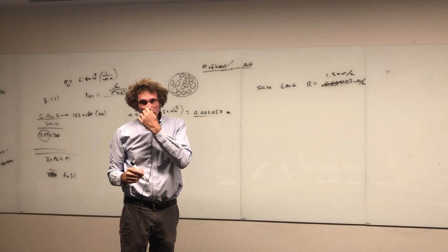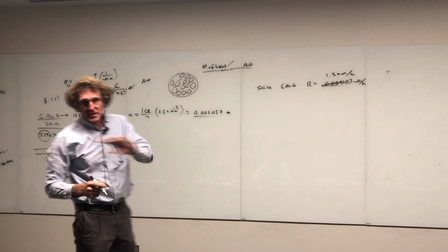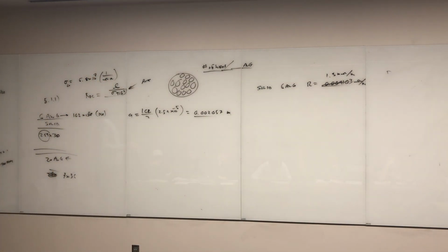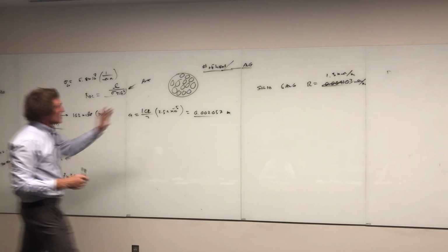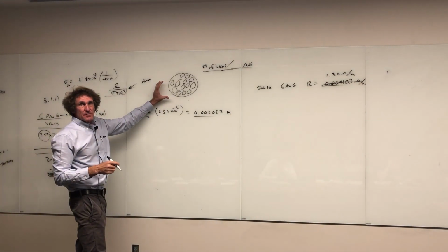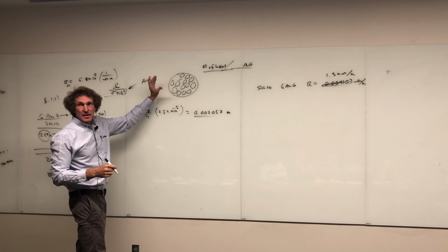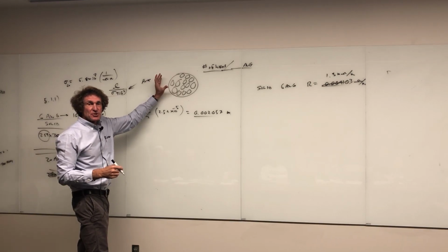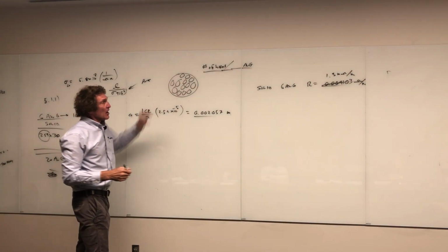Please make sure you see this. You're going to see this again. All right, stranded wires you're going to run into in bundling all the time. Almost all the stuff that you get with Cat5 cable is bundled stranded wire. Lots of other things. Whenever you have electronics with a lot of different IOs and stuff like this, you'll see all the stranded wire, and it's bundled. Usually, well, it depends. If it's an electromagnetic noisy environment, then they actually bundle this and put a shield on it. Okay?